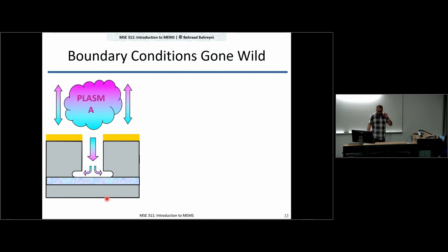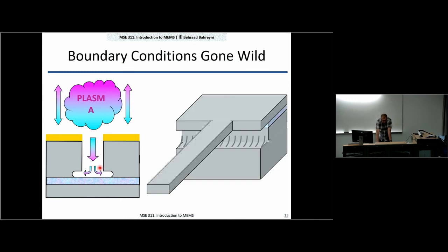Now, boundary conditions that we are applying here are really simplistic. They are only considering the simplest, ideal situations. For MEMS fabrication, you can have situations where the material is not really going to maintain its uniform cross-section for you because of, for example, the undercut you may have at the interface between different materials.